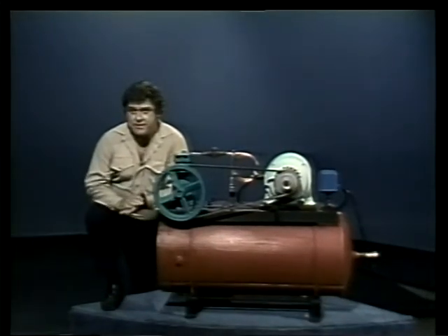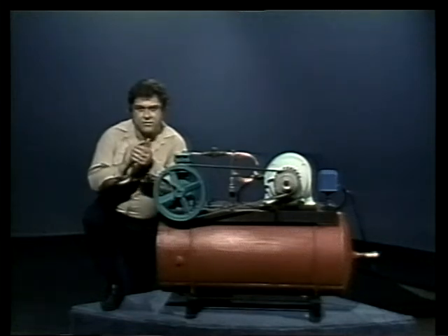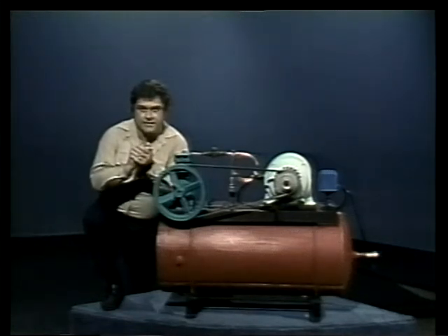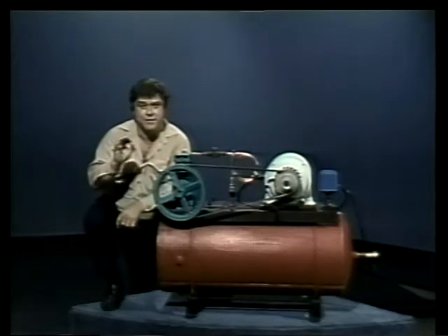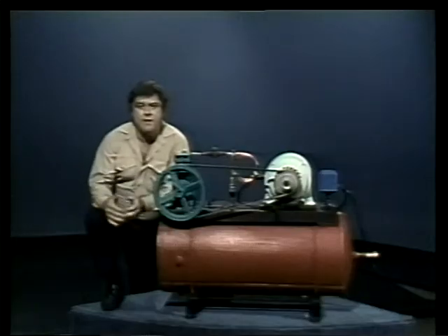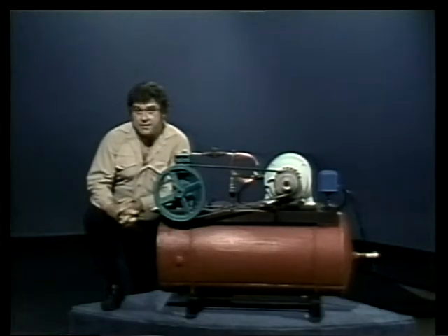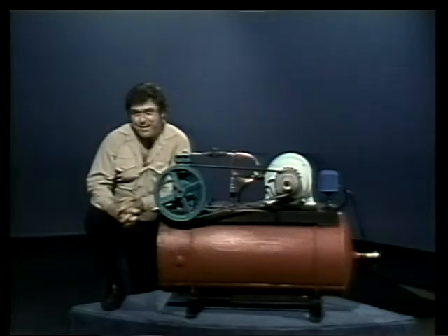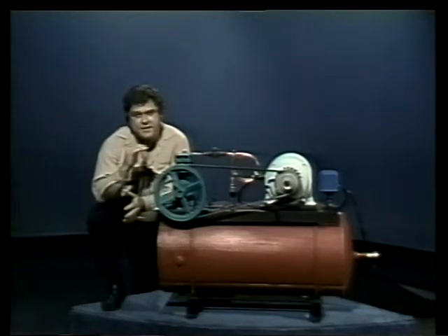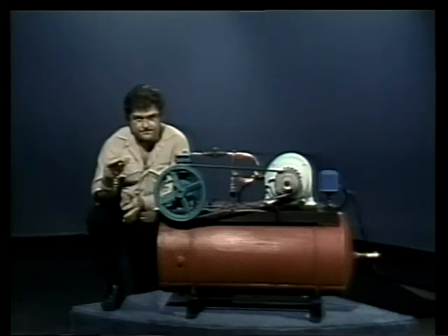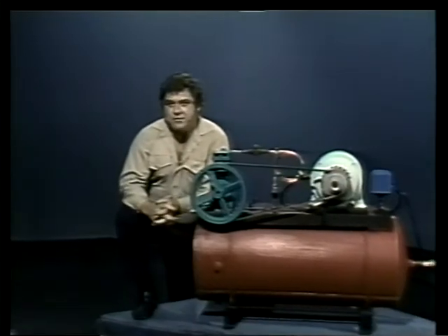Positive displacement compressors confine a mass of air and squeeze it, raising its pressure. Dynamic compressors speed up the air, giving it extra energy that's converted to pressure when it slows down. Another difference between positive displacement and dynamic compressors is their typical capacity. On the average, positive displacement compressors are rated for higher discharge pressures, but the average dynamic compressor tends to have a higher flow rate.